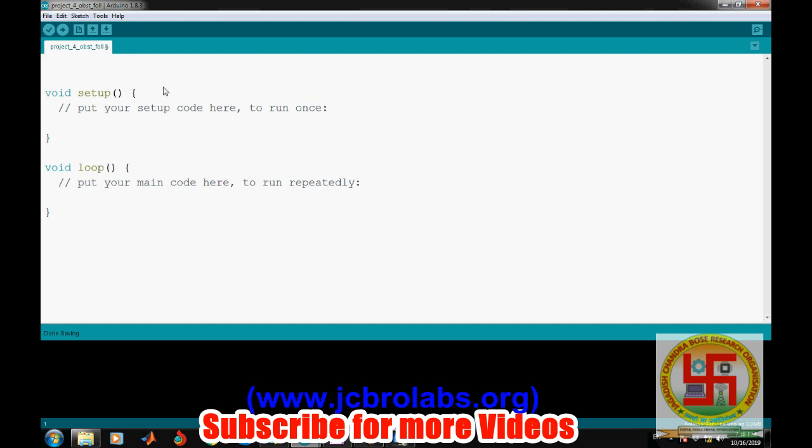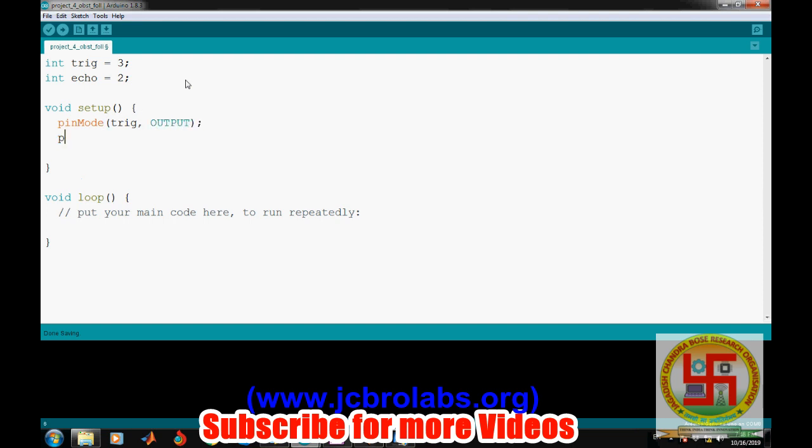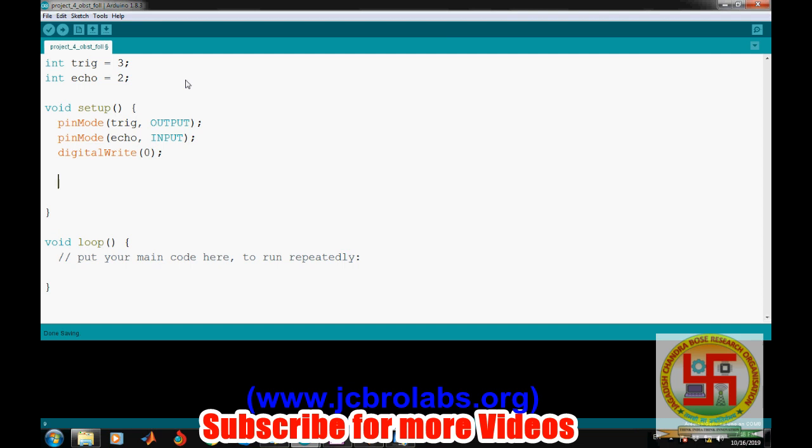Right, so let's save it. Now first of all we need to define the trigger pin. The trigger pin is connected to pin number 3, and the echo pin is connected to pin number 2. Now in setup, we will first initialize the pins. Trigger is an output pin and echo is an input pin. So pinMode trig, comma, OUTPUT, and pinMode echo, comma, INPUT. Right, and let's set this trigger pin to 0, so that it remains 0 at the start. And in order to see the distance calculated from this ultrasonic sensor, we will be sending data to the serial monitor. So Serial.begin, let's say at the rate of 9600.